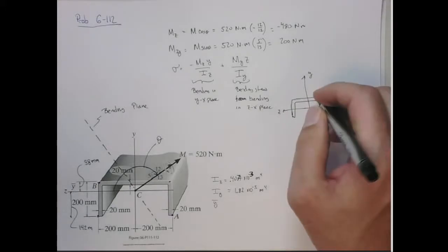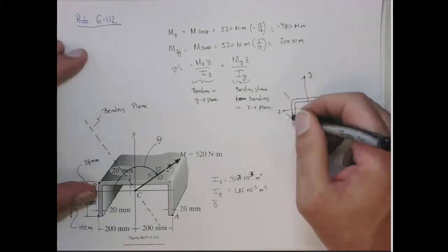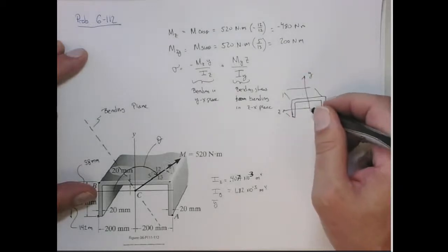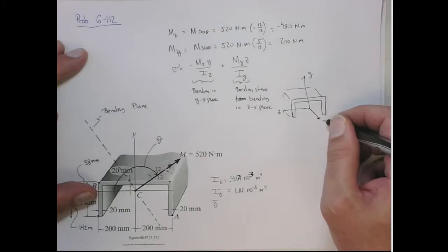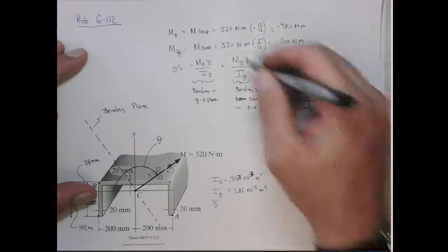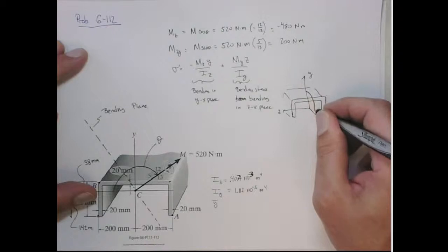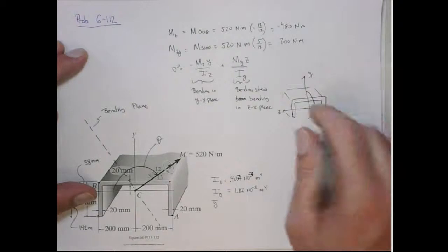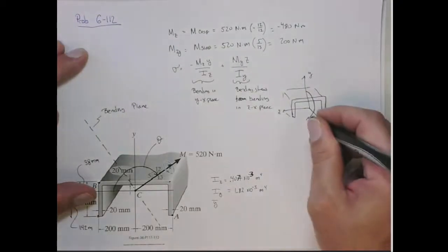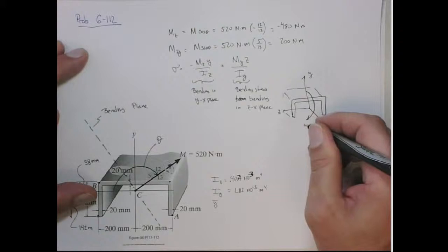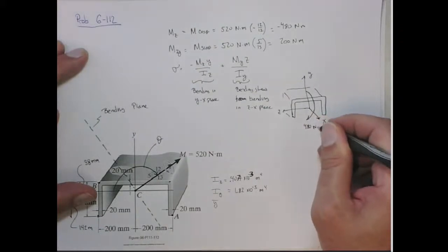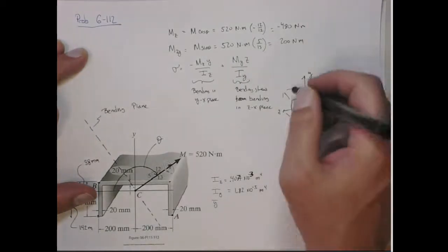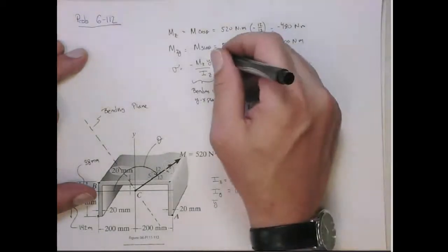So that's, I always have a tough, let's draw this. So it's a little 3D looking. And here is the x-axis. So this would be as if we had a bending that went around like this. Let me get the sign right. It's a minus 480, so that's actually going down this way, right? Where this is 480 Newton meters. All right, so we figure out the stresses in that situation. This is what's giving us that term.